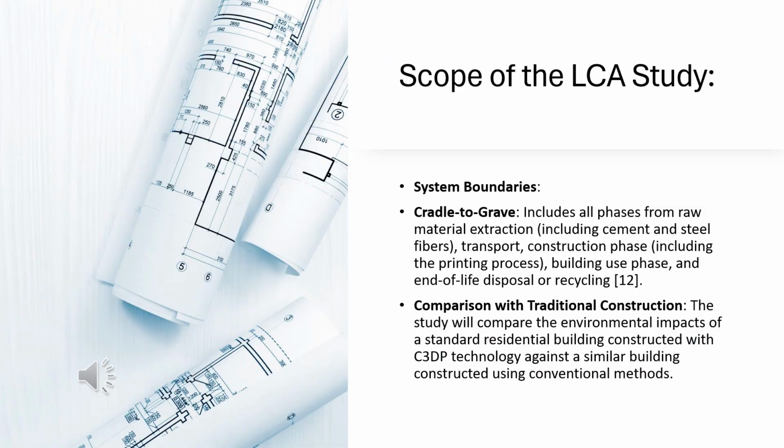Scope of the LCA study. Cradle to grave includes all phases of raw material extraction, including cement and steel fibers, transport, construction phase, including printing process, building use phase, and end-of-life disposal or recycling.